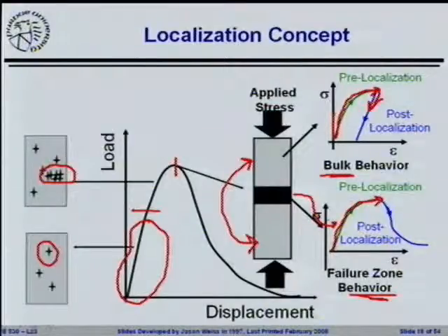But inside of the cracked region, that crack is going to start opening up, and that crack is going to open up and it's going to be able to transfer less and less stress. So what's happening is the amount of stress that it can transfer is decreasing as you open that crack further and further. And this kind of makes sense. Imagine if you had Velcro and you start to separate that Velcro a little bit apart. That Velcro is not as tightly bound as if you really get it in there and mush it tightly together. So as the cracks begin to open up, they can transfer less stress across the cracks.